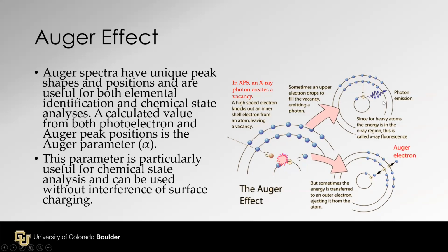For most of the cases, this photon energy belongs to the X-ray region, therefore it is X-ray fluorescence. In X-ray fluorescence, XRF, the incident is typically X-ray in and X-ray out. This is also EDS, okay? In an EDS system, the incident is an electron beam, and we detect the characteristic X-ray photon to determine which element it has.